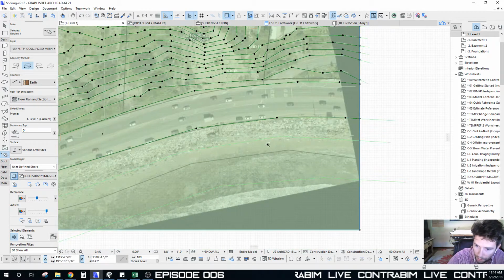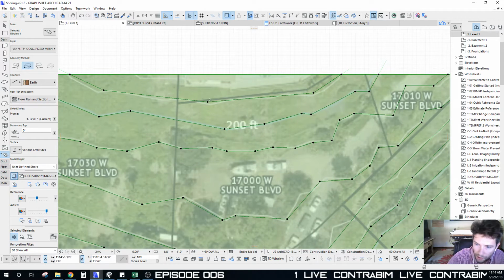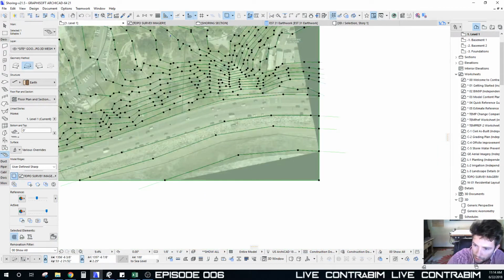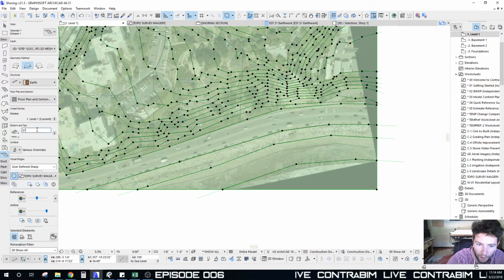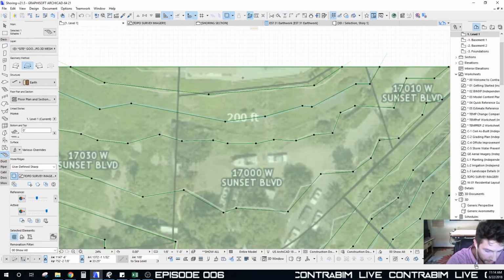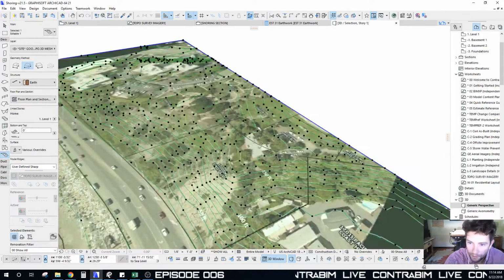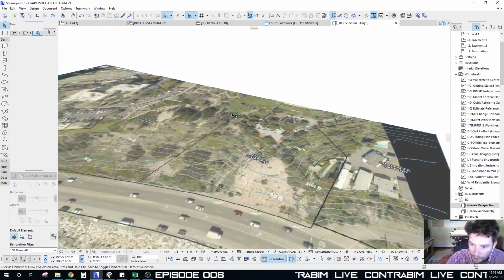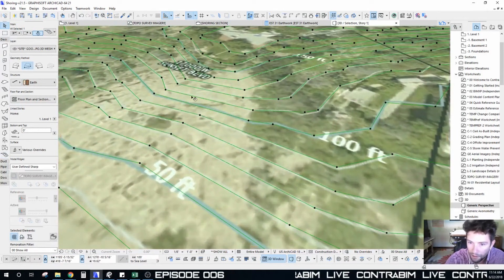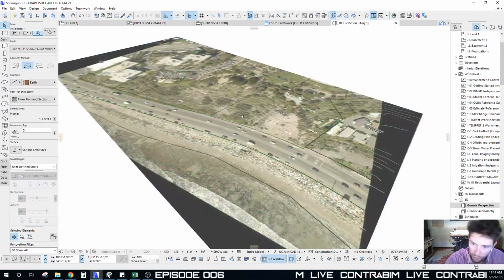So okay, we're almost done here with just adding in these lines. If we look at our scale here, we're going from essentially up here 210 feet down to our sea level, and our base level here is set to 0. So okay, at this point, if we go to 3D, by hitting F5 in this case, since I'm on a PC, we can see all those lines are in there, and we can see that they're very well meshed up with the topo lines that we had from our source imagery file.